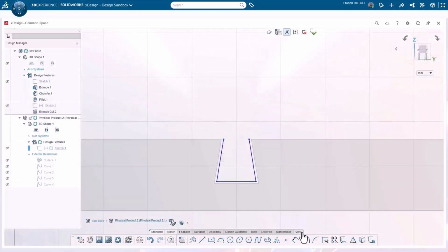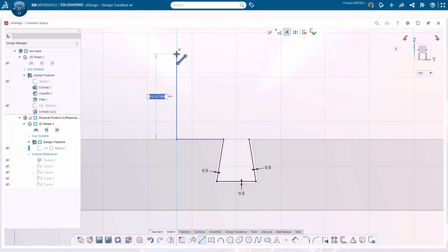Take extra care in designing the dovetails. Every 3D printer has different tolerances, and even the print orientation can play a role as to how they fit together. With my setup, a clearance of 0.5 millimeter on each side gave me a good tight fit.